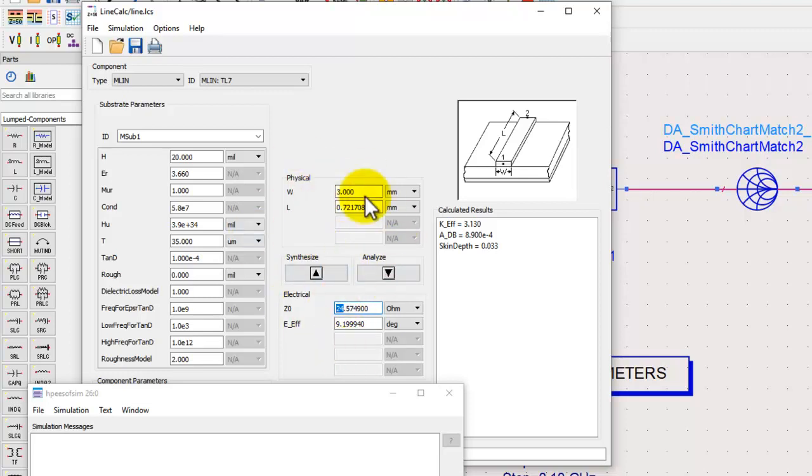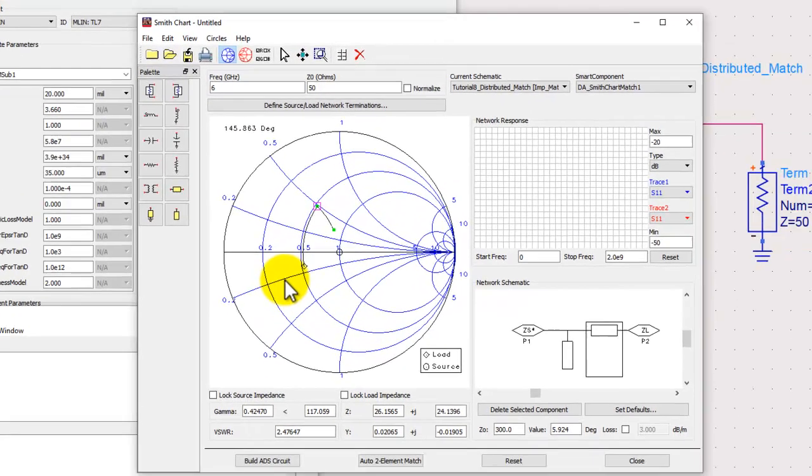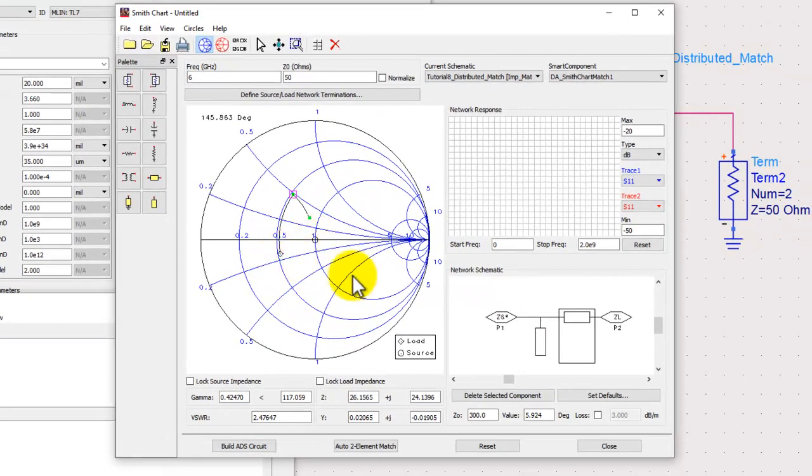These are very important practical considerations which you need to take before you jump into the world of impedance matching. Well, now I know my bounds. I have my source and load, and remember this load is the same one we used earlier, 26 minus j6.7. If you haven't watched tutorial number 6 and 7, please go ahead and watch that. So we lock load and source, and let's go ahead and change this line to what we calculated.